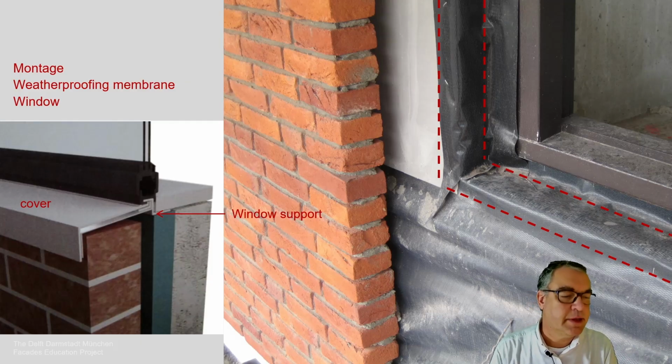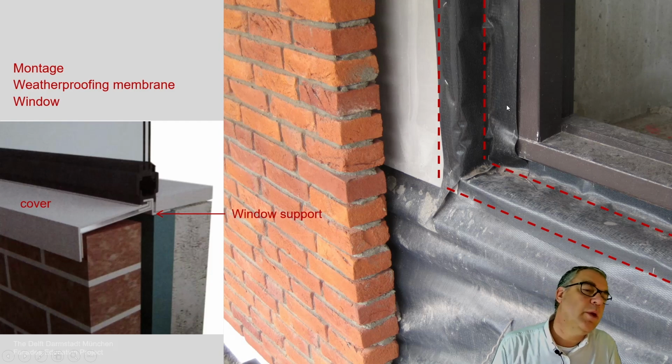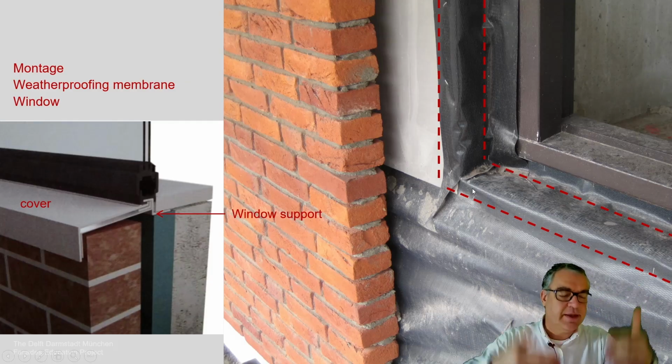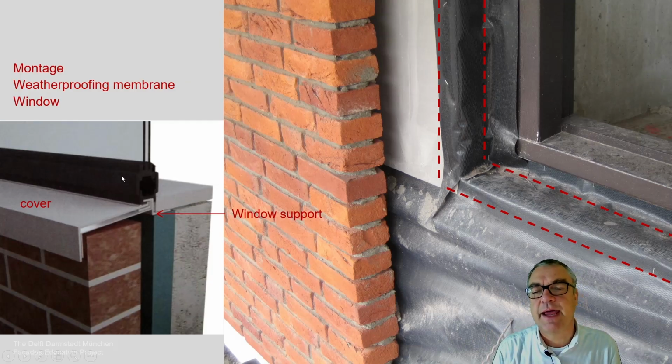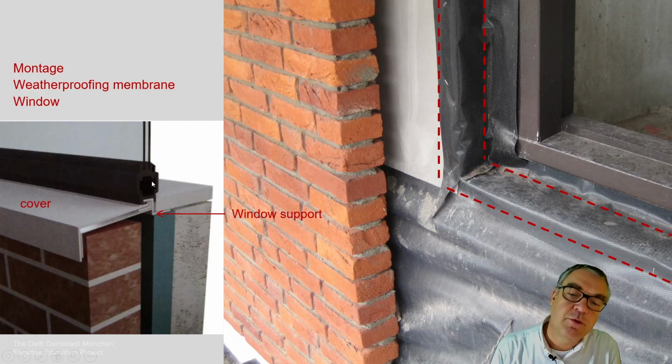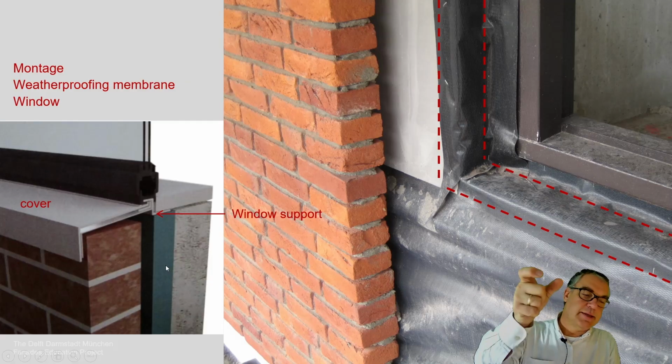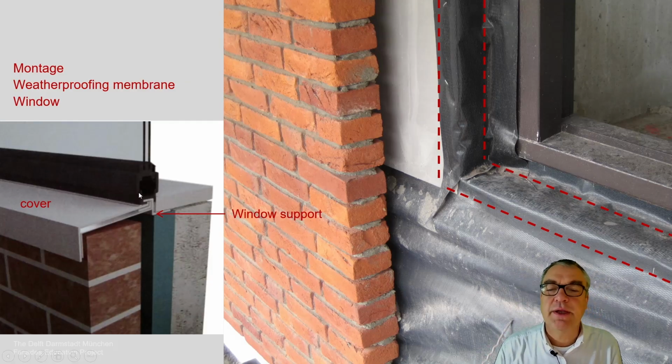Same technical detail. We see the masonry structure, we see a window being brought in position, and we can identify that this needs to be positioned so that any leakage does not penetrate the inner insulation and stays in the system and then finds its way out of this structure. Same for this situation, left picture. Here we see the window frame being brought in position. They always have to be brought in position in a similar area of the insulation.